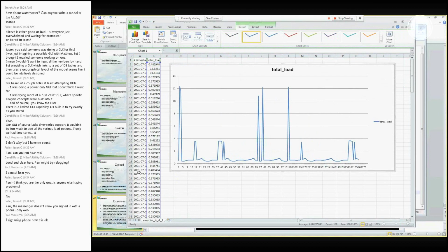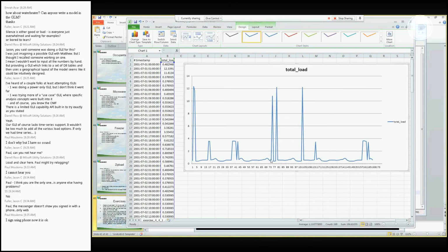So this is, I think I ran this for a week. This is what the load shape looked like for a week, measured on 1-hour intervals of the actual power. Now, of course, one thing to be careful about when you're looking at the total power, those are instantaneous measurements and not energy measurements. So in this case, it's running every hour. So there's always chances that you can capture a period where the entire HVAC system is on. In this case, it's a resistance coil heating unit, and a 12 kilowatt resistance coil heater is not that common, but it's a setting that you can do on there.